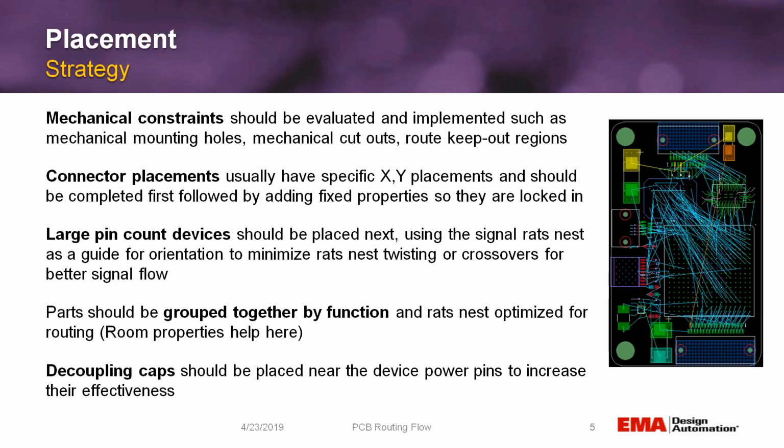Then the last part would be placing all your decoupling caps, and obviously we would want to place those in close proximity to their device power pins to increase their effectiveness.